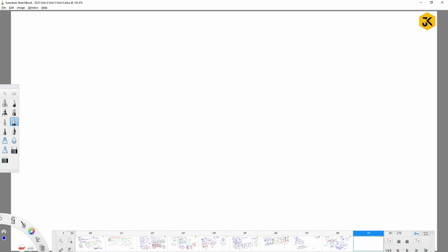Hi everyone. In today's class, we'll see one of the asynchronous counters, that is a mod 6 counter. Guys, you know what is the meaning of mod 6 counter, right? Mod 6 counter means it is going to produce the values from 0 to 5. If I have the value 0, then I will get the value 1, then 2, then 3, then 4, then 5. Again I come back to 0. This is what you can call a mod 6 counter, right?